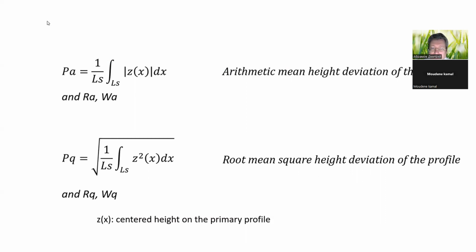Ra is probably the most well-known parameter and the most used in specifications. It does not mean that it is the most useful or meaningful, far from that. But it is usually the only one known by designers, and often the only parameter taught to students. Using Rq instead of Ra would provide similar results but with a physical meaning. Rq, as the standard deviation, or in the variance form, is found in several tribology equations.